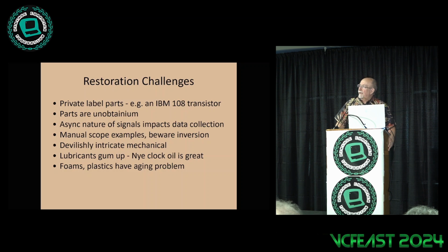Then whoever selected the oils, the greases, the foams, and the rubbers for IBM's 1960s products made some very bad choices. Very bad choices. The oil and the grease will collect dust and turn into cement. So if you have an old Selectric in the closet and you haven't run it in a while, and you turn that typewriter on, it's going to be frozen solid.